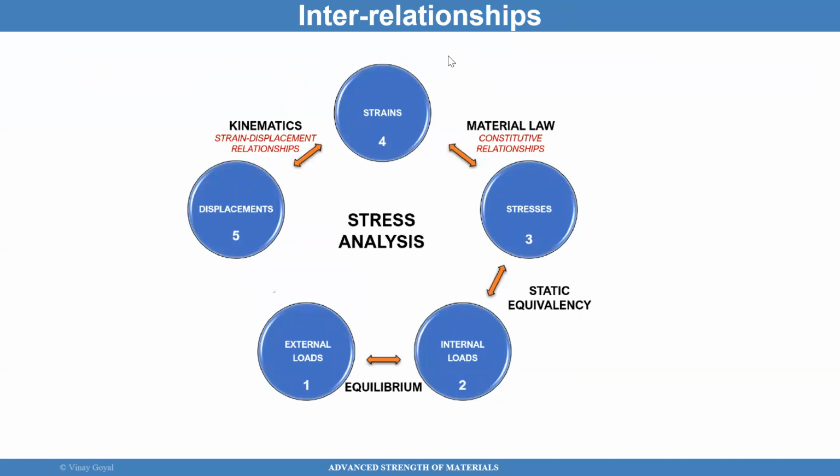External loads are provided to a system. In this case, when two bodies of materials are coming into contact, the external load is caused by these bodies of materials coming into contact. That produces an internal load within each of those bodies of material. And we're looking at when these bodies of materials will fail when they come in contact. You'll get stresses internal to the structure for each of these bodies of material, and then you have strains and deflections that can be calculated because they're all connected with each other through this map that I have been covering that came from my book.